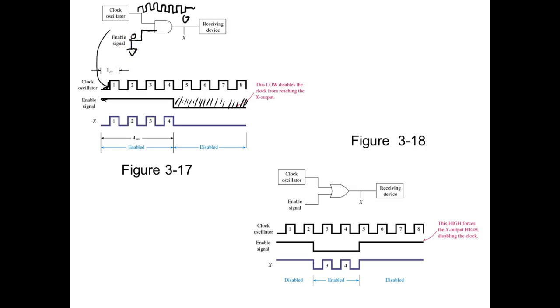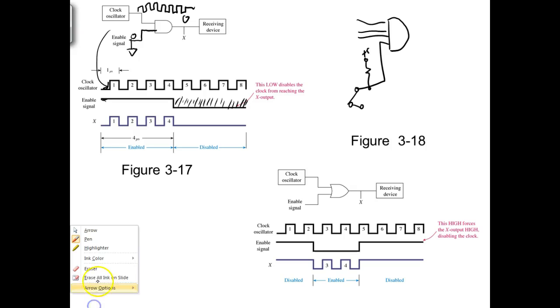So if this input right here is a 0, I don't care how many inputs I have on this AND gate, right? You understand? So if I come over here and I have a 4 input AND gate, and I take this one right here, and I'm going to put a pull-up resistor right here because I cannot put a nothing on here, right? You understand that? And I'm going to put this to plus 5 volts. In fact, we don't have to do that.